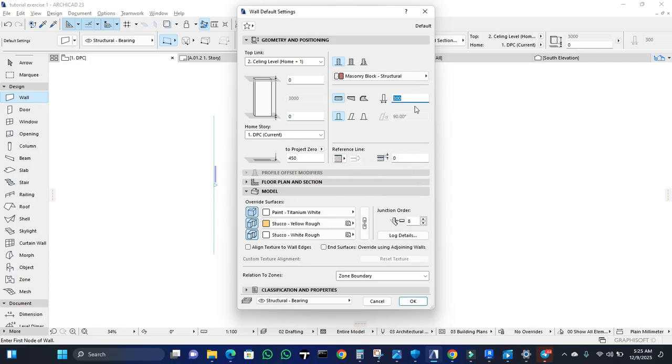So now we are going to be starting with a basic bungalow, just a simple, let's say 2-bedroom bungalow. You have to see a parlor, a kitchen, a dining, and 2 rooms. So that's what we are going to be doing. And for that structure, we will be needing just 6 inches blocks, which is the metric equivalent is 150 millimeters.